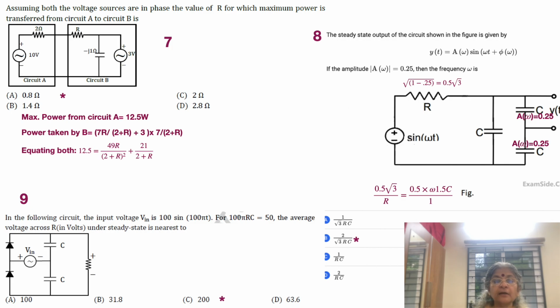If this is clear, now we can move on to the rest. We now need to explain that the current through the resistor is the same as the current flowing through the capacitor assembly. What's the current through the resistor R? It is the voltage divided by R. So 0.5 root 3, as we computed right now, divided by R is equal to the current flowing through the combination.